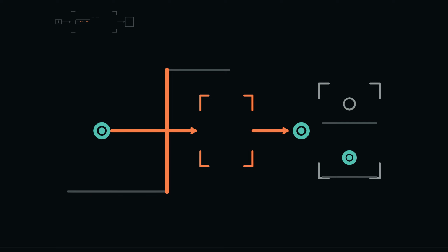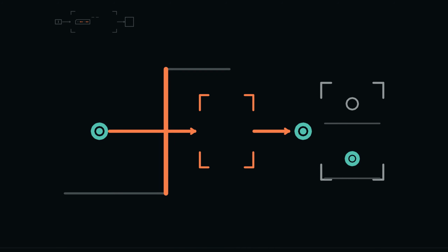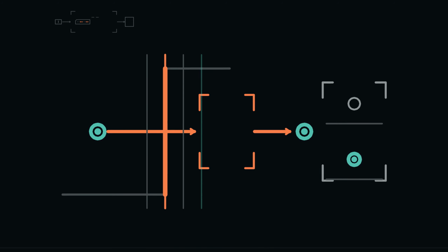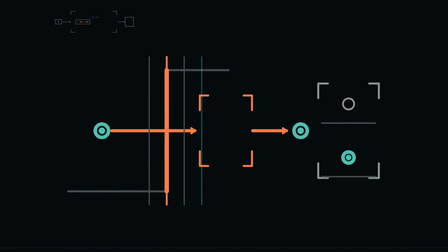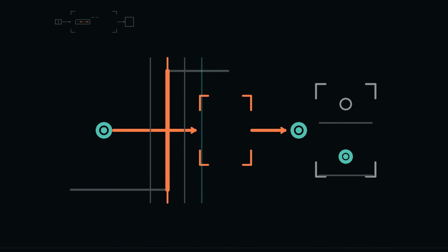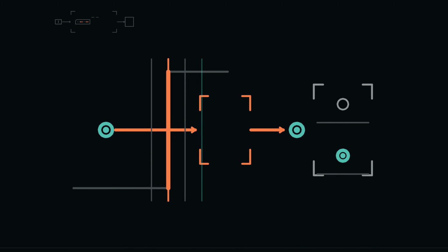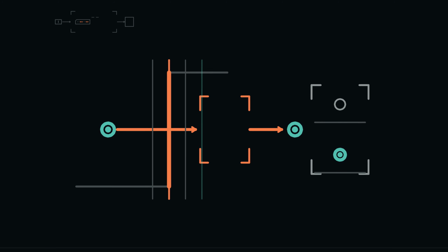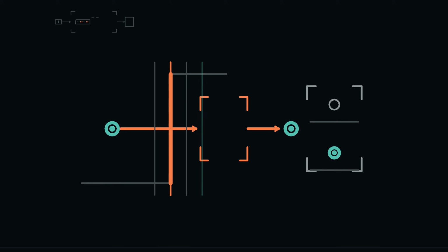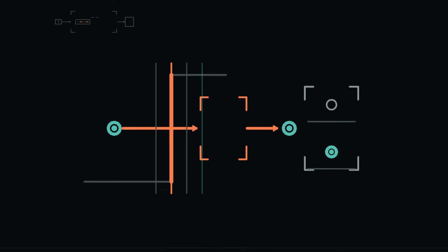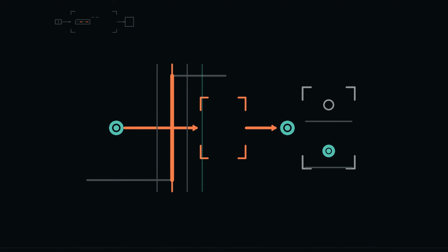The held output separates a proposal for the future from the state the machine currently owns. For capture to be guaranteed, D must be stable for a specified interval before the active edge. That interval is setup time. Think of it as a forbidden last-moment arrival zone on the timeline, not as a command to slow the data artificially. If D changes inside that zone, the storage element's contract does not promise which value will be captured.